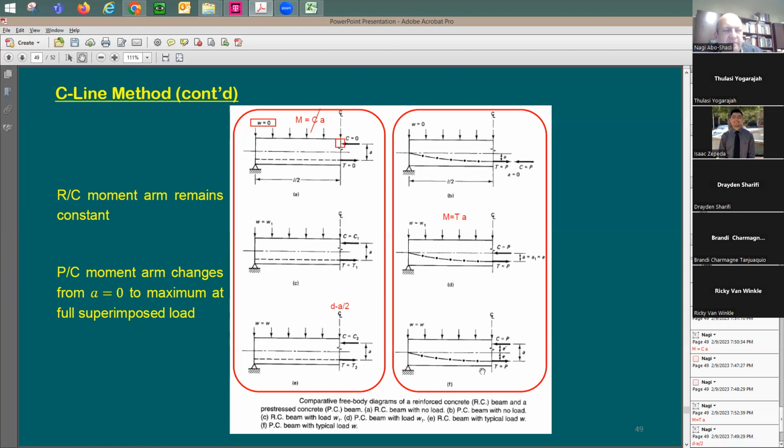Look here what happened. The amount of pre-stressing that you put here at the beginning is not changing when you're adding more loads, which is kind of weird, right? I understand that I add more load, I need to see some stresses, some forces in the strands or in the reinforcing bars, and some compression force is going to grow up.